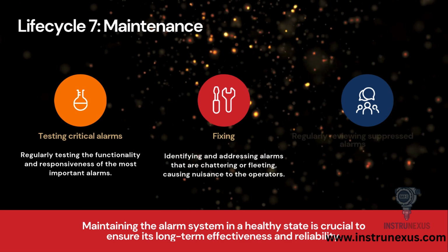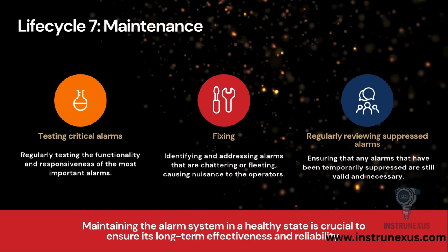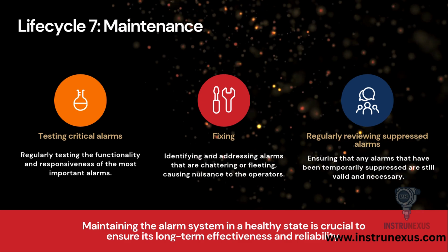We also need to regularly review suppressed alarms. If an operator shelved an alarm for maintenance, we need to make sure it gets turned back on. Maintenance ensures the long-term reliability of the system.